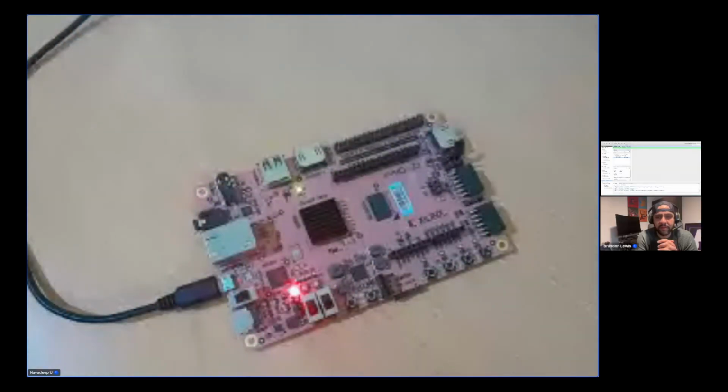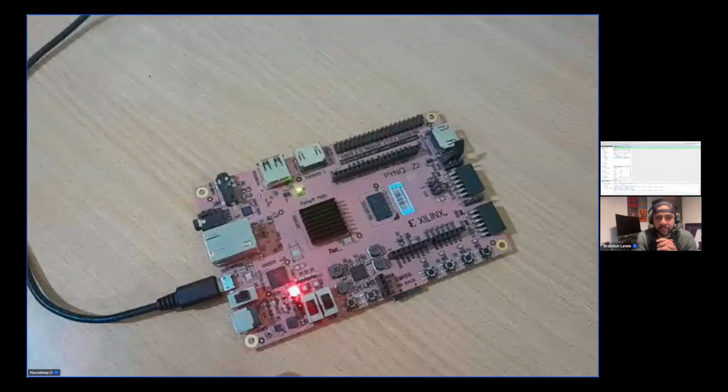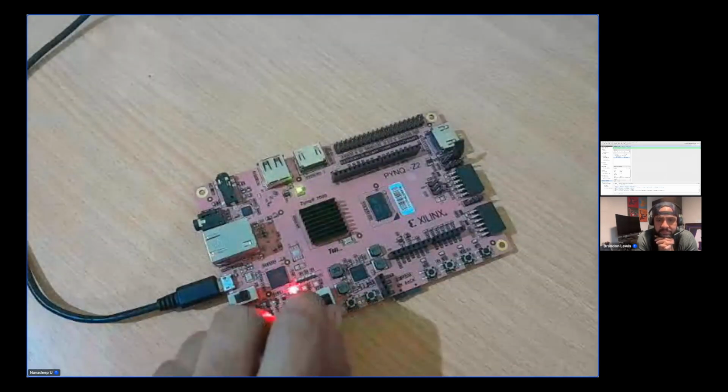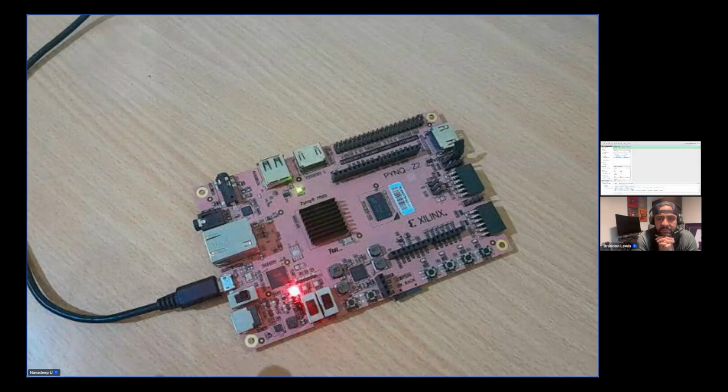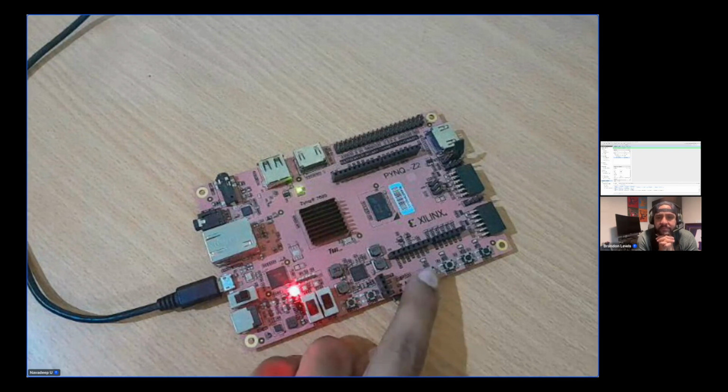if we look at the device state now, it's again evident that all the LEDs are off. And if we go to 0-1, that's the first state, there are no LED trails. This is for a reason: we have cut the clock and the system just waits for a positive edge of the trigger, which is the user input tick.